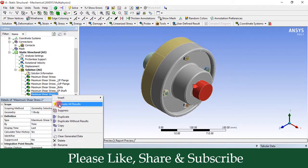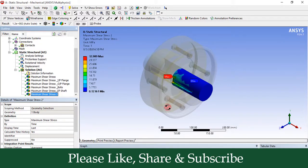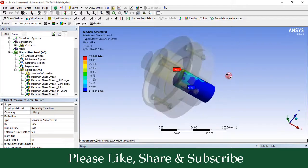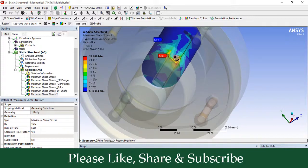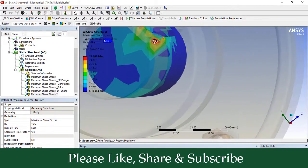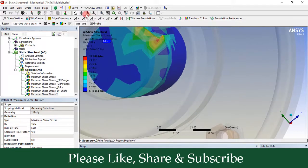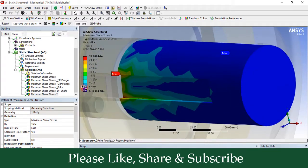Right click on it and click on evaluate all results. So our solution is ready for output shaft. Again, you can see here the maximum shear stress point is same as that of input shaft. Its location is same, that is the point at which the slot is present, that is the point at which there is a sharp corner in the shaft, and the sharp corner is present in the slot region of keyway, that is at this point, and the minimum stress in this shaft is here.